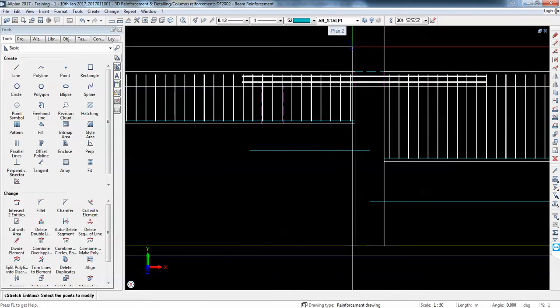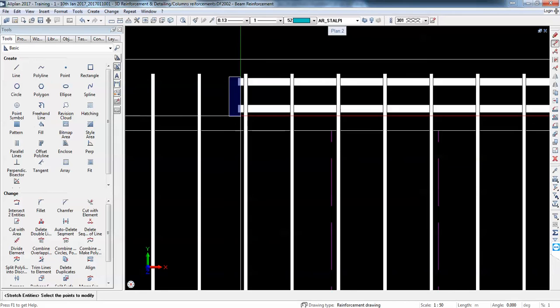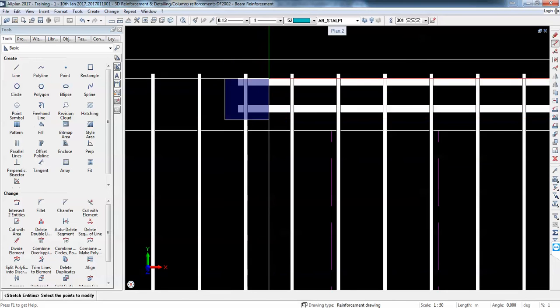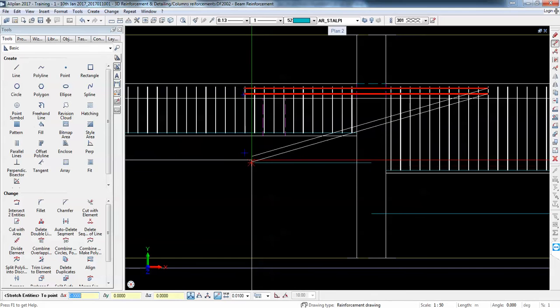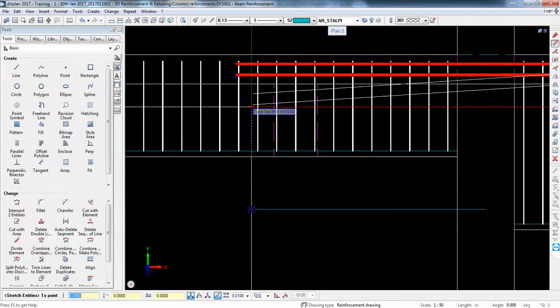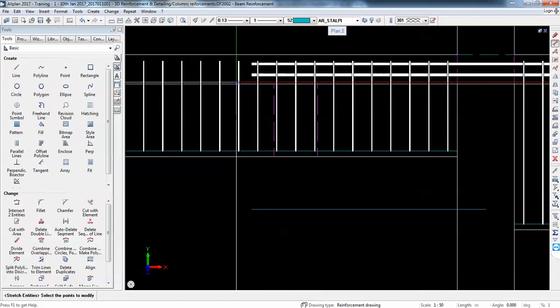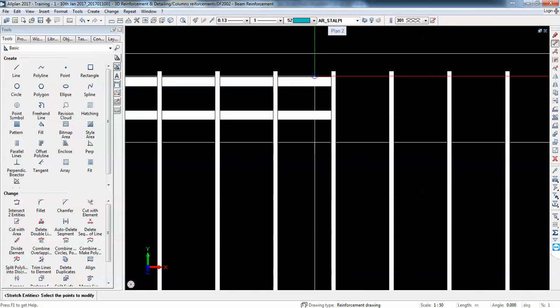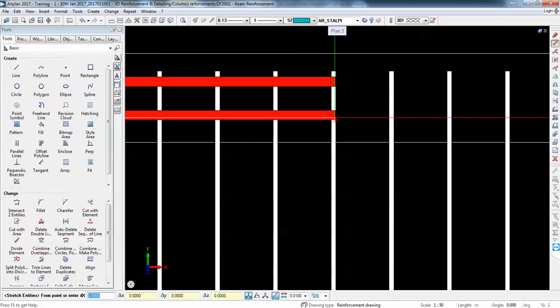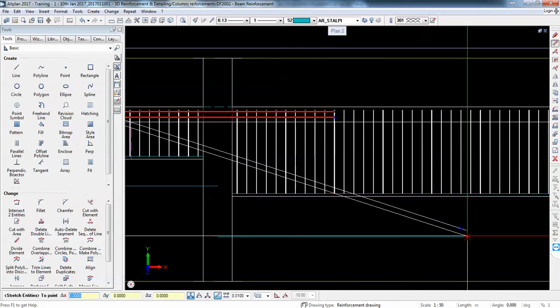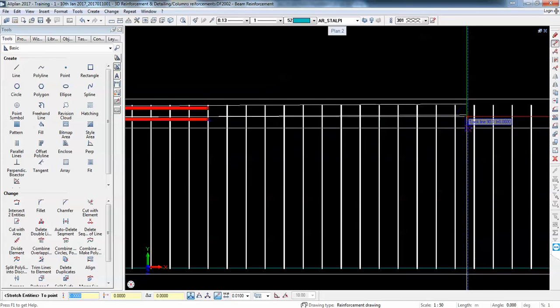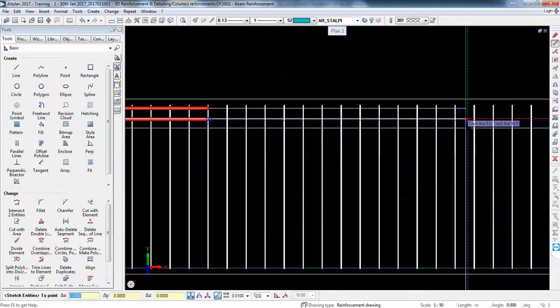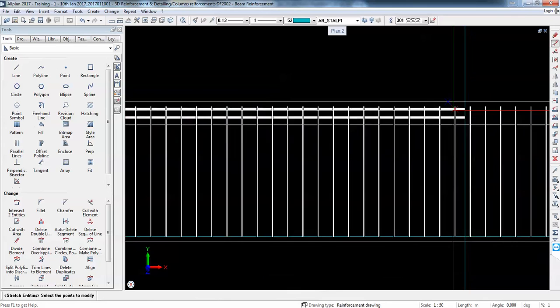So this is how we work. We just create the first bars. I hold this indicator so I know how far should I go. I hold here as well without clicking, hold further, and it will detect the intersection. You can see track line 0 with track line 90.